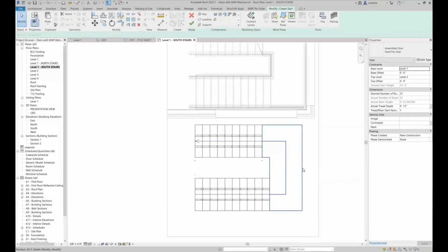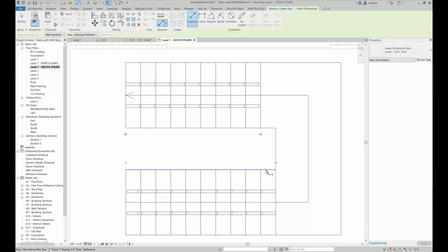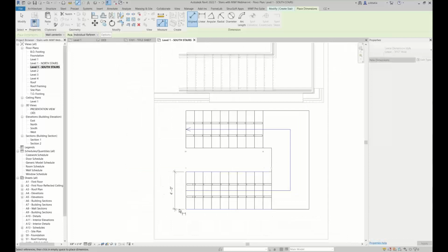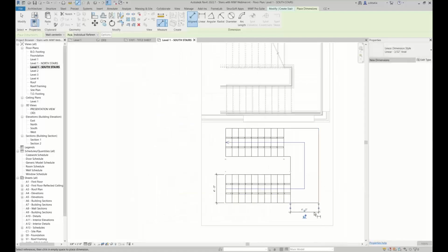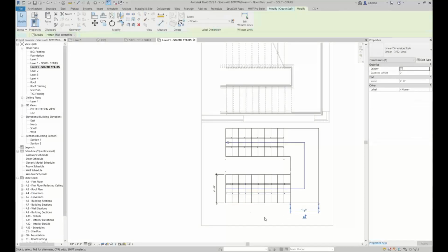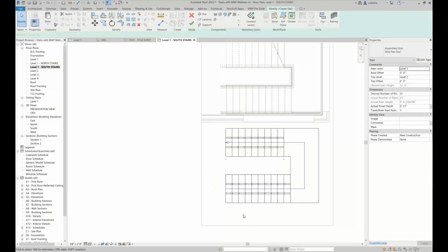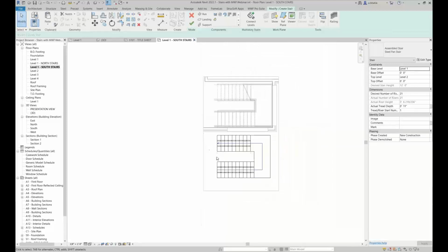We're going to just ensure that our stair width is 4 feet. By code, we need our landing width also to be a minimum of 4 feet because it has to match whatever our width of our stairs is. So we're going to leave it at that. It seems to match right now, and it's all looking great. So once we finish this, our stairs are complete.